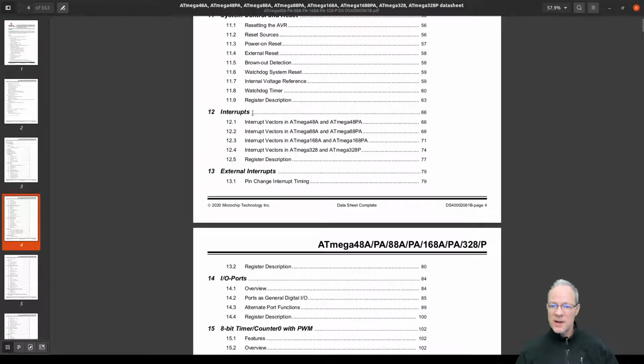Now the next section is about the interrupts. The system on chip, it can work on itself. It can do computations, solve the problems, but it's really meant to work with the outside world. It is meant to be event driven from the outside world. And these events can be of all kinds. It could be just when I bang on my keyboard. So each keystroke can be an interrupt to that device. And whenever I push a key, the device looks, aha, this key was pressed, so that means I need to run this function. Things like that.